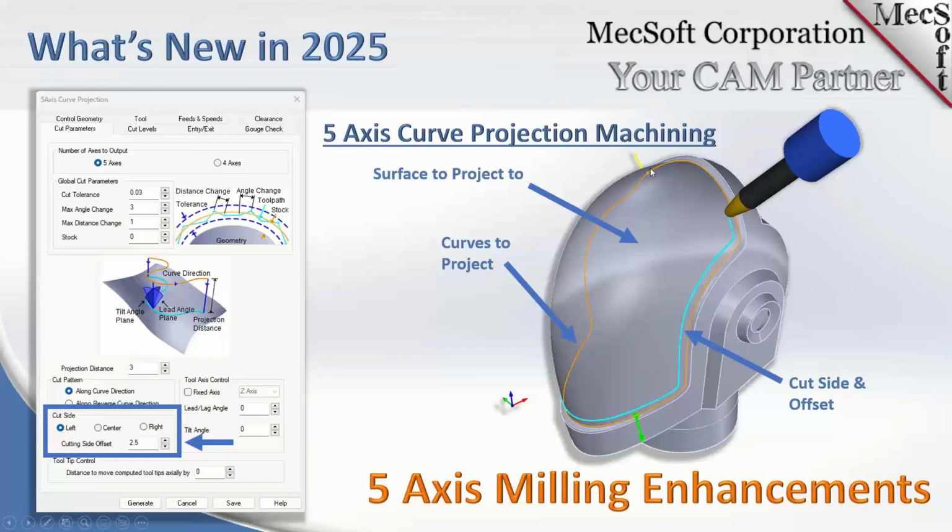If you tried to go in here and draw this offset curve, you would not get a good result because of the complex area this is in. Trying to offset it and then project it is going to be a problem. So you're probably not going to be able to use this method in previous versions. So now we do this as part of the toolpath. It's very, very helpful, as you can see in this particular part itself.